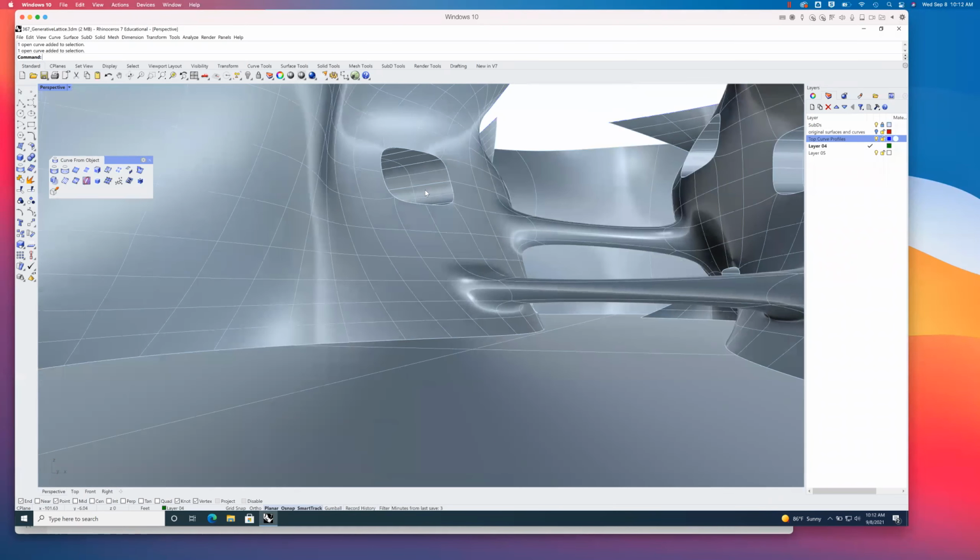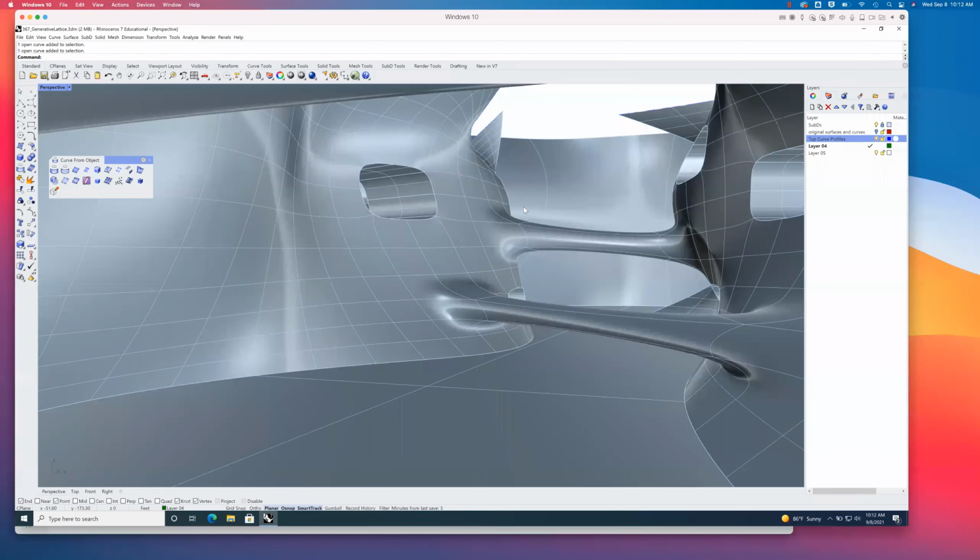I don't know if any of you are photographers, but if you look at the sort of camera that you're looking through, when you're looking through your viewports, particularly with your perspective view, think about it as a sort of DSLR camera, right? If any of you are good at photography, you know that you can change that zoom, and you're basically changing the lens length, right? And right now, by default, our camera for our perspective view, the lens length is set to 50 millimeter, which is actually kind of tight.